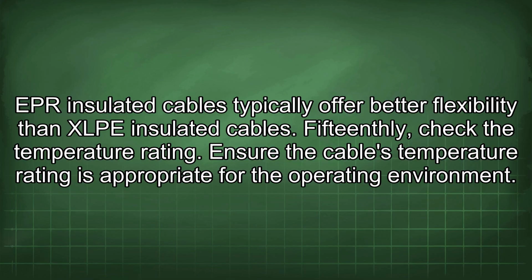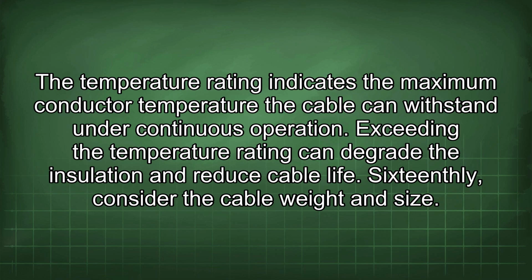15thly, check the temperature rating. Ensure the cable's temperature rating is appropriate for the operating environment. The temperature rating indicates the maximum conductor temperature the cable can withstand under continuous operation. Exceeding the temperature rating can degrade the insulation and reduce cable life.